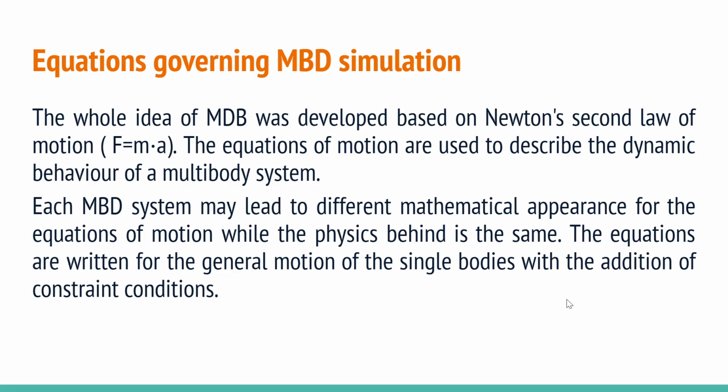Equations governing MBD simulations. The whole idea of MBD was developed on Newton's second law of motion. The equations of motion are used to describe the dynamic behavior of a multi-body system. Each multi-body system may lead to a different mathematical appearance for the equations of motion, while the physics behind is the same. The equations are written for the general motion of the single bodies with the addition of constraint conditions. So come to the next slide.